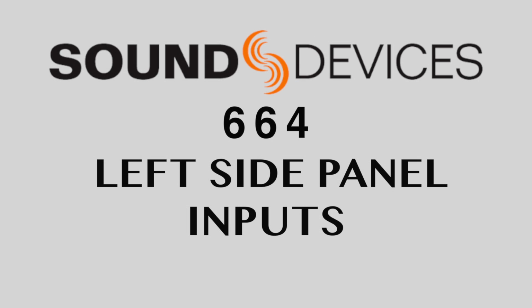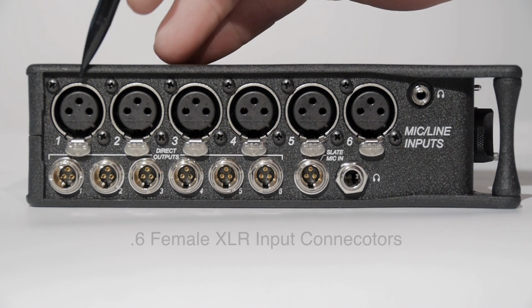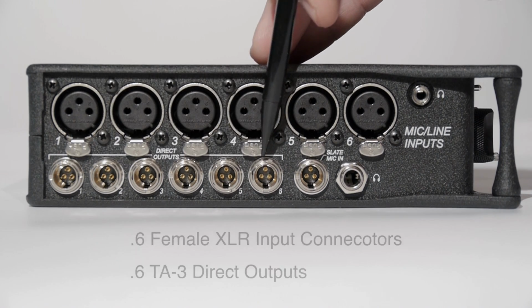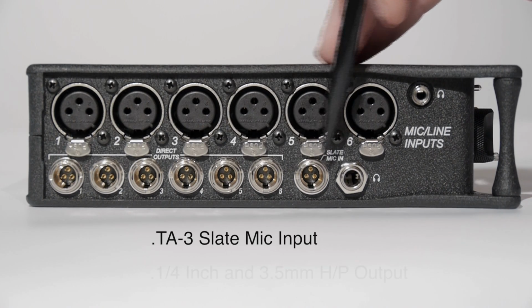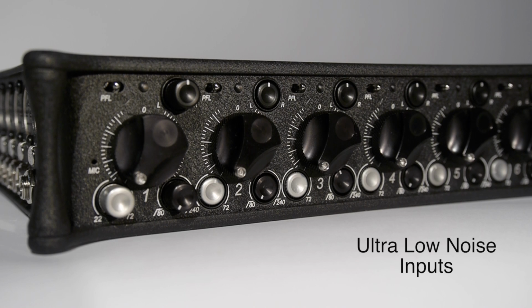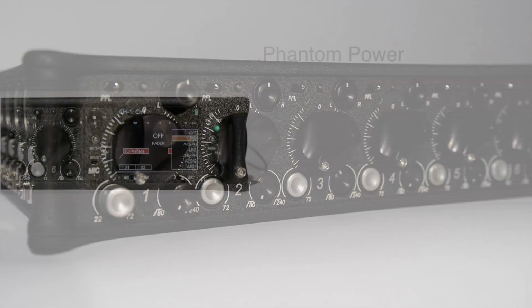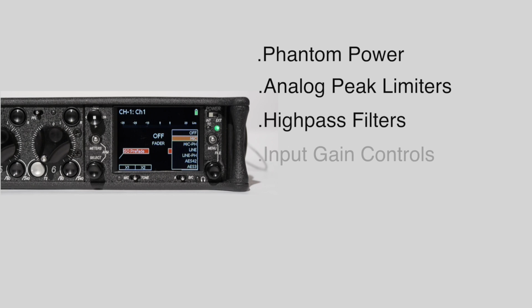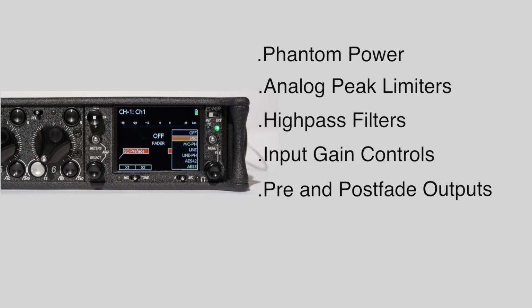On the left side panel of the 664, you'll find 6 female XLR input connectors, 6 TA3 direct outputs, a TA3 slate mic input, and both 1/4 inch and 3.5mm headphone outputs. The Sound Devices 664 has ultra low noise balanced analog inputs complete with phantom power, analog peak limiters, high pass filters, input gain controls, and pre or post fade direct outputs.